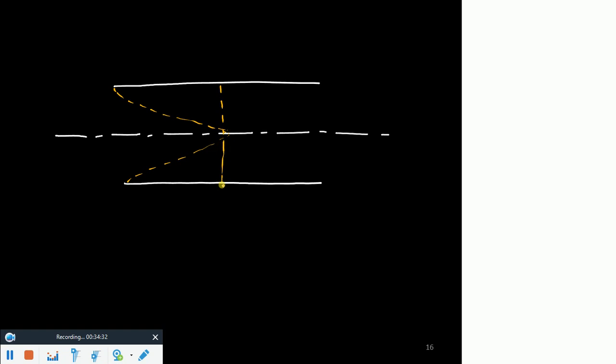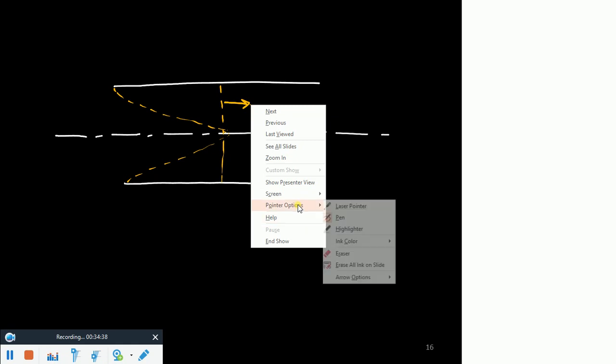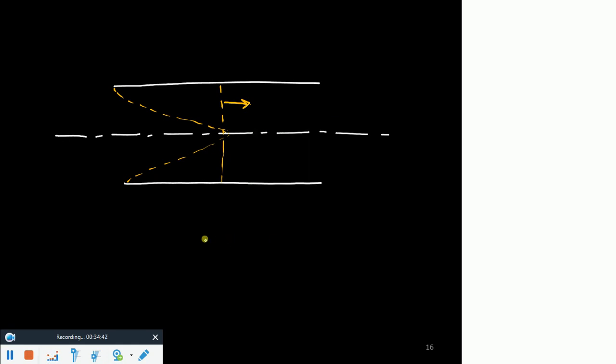So beyond this point you have what? Hydrodynamically fully developed region. But if you talk about a fluid which is not having Prandtl number equal to 1, or it is having some different temperature, some different properties, this may be the point where you have thermally fully developed region.